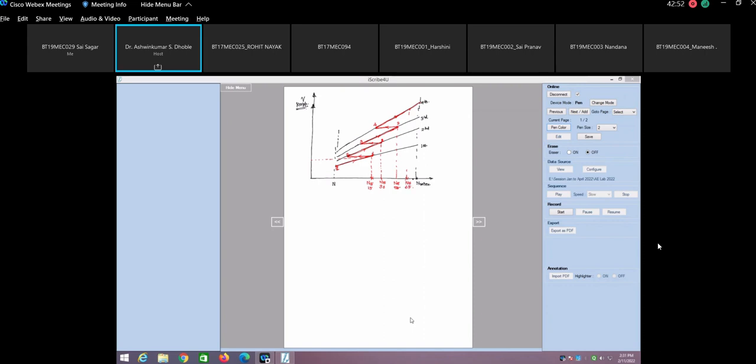So this is basically the red color here, whatever we are drawing here, that shows the gear shifting pattern for your kind of vehicle. This is for transmission efficiency of 100%. So similarly, you have to do it for transmission efficiency of 95% and transmission efficiency of 97%. So sir, आपके पास ऐसे 3 ग्राफ आएंगे.